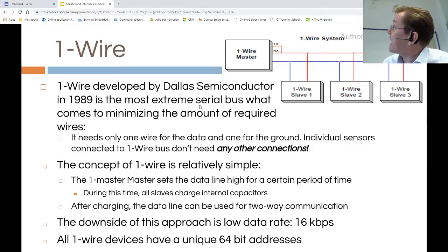Okay, so this actually has the transmit and receive signals on the same wire, which means that, of course, one device can be present at or sending data at a time, so it means that it has some protocol issues. As soon as you put more than one component, one sensor, you first must go through the device discovery before you can access those sensors.